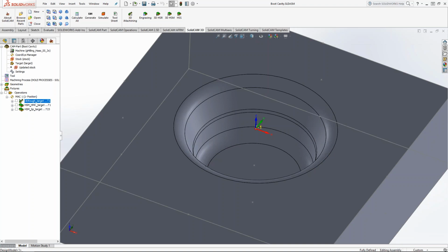Okay. So with that coating, the wear was pretty good. I could generally get through semi-finishing and finishing tool passes with one tool, depending on the size of the cavity and core. Sometimes I may have to change over if it was a bigger cavity, in the 24 by 18 range. I may have to do just half of it and then change the tool and do the bottom half with another tool.